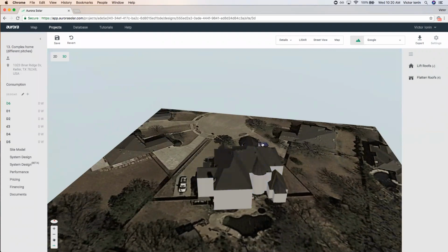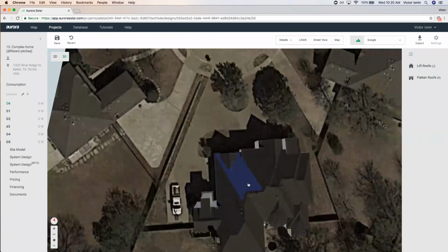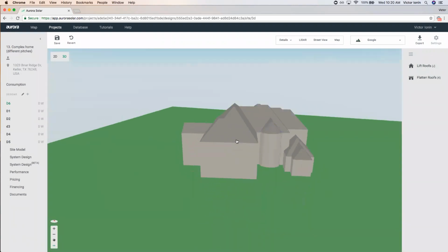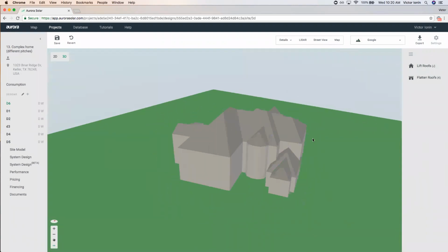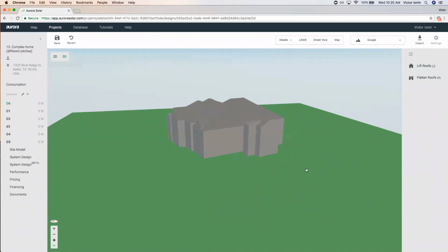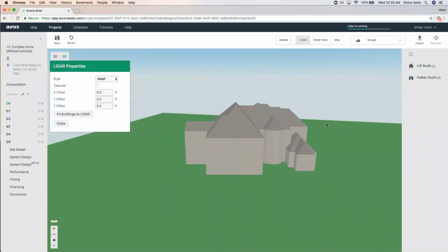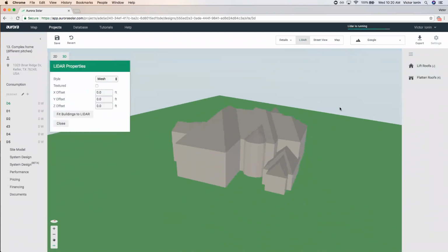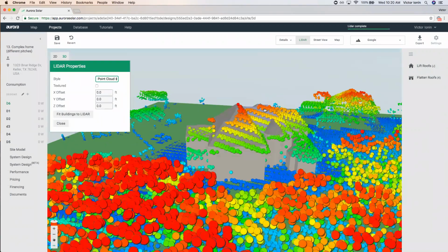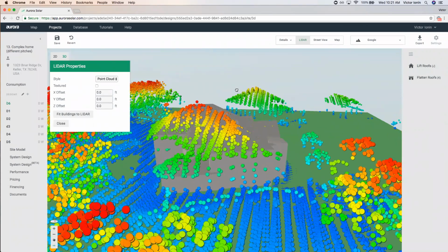That's not required though. So I would always try and use some of the more basic hints first to draw a complicated roof. But if you really wanted this as one piece, you have to be mindful of the tilt of the roof. You have to be mindful of the height of the different eave lines. And once again, I would probably use LiDAR to help me with that, right? Because LiDAR actually tells you easily that there's two different tilt values. One's less steep than the other.